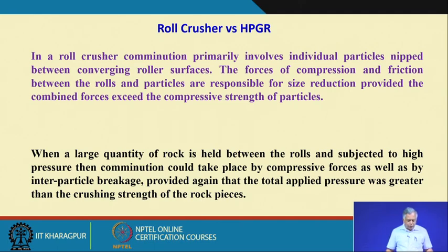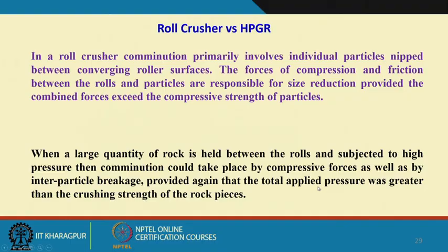When you are putting in pressure energy, you have induced some internal breakage or internal cracks, and that pressure energy travels through those cracks and may keep on creating more cracks, provided again that the total applied pressure was greater than the crushing strength of the rock pieces.